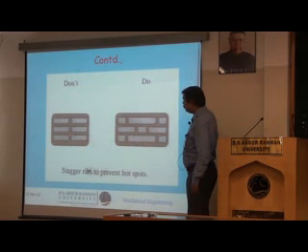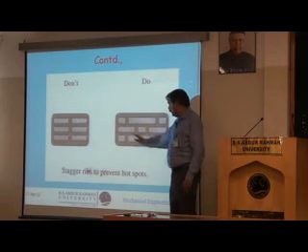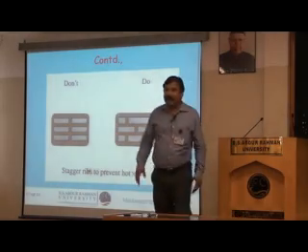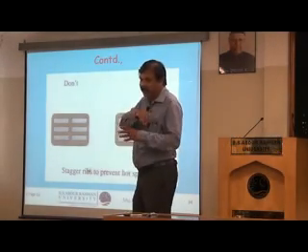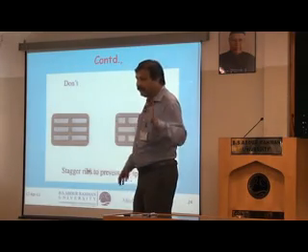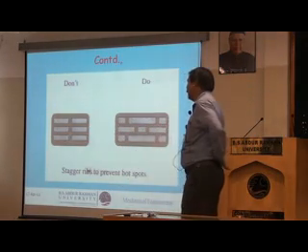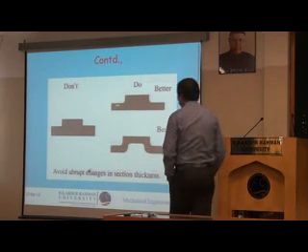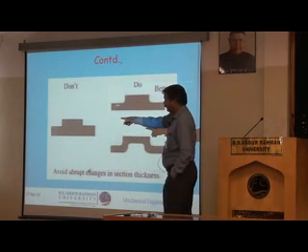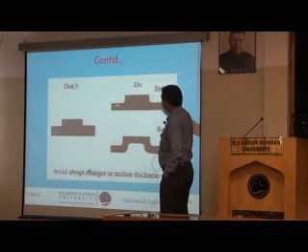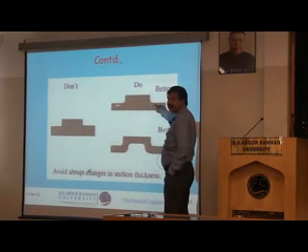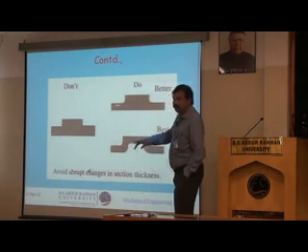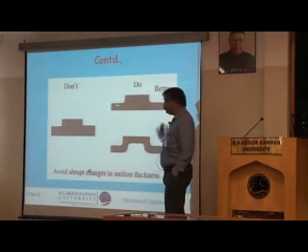Next. And similarly, ribs are to be staggered. When the ribs are aligned, that will provide a continuous discontinuity, and that is not preferred. All the ribs are to be staggered. Next. So that is one thing. There is a sudden change in cross section. This is better because I have provided a fillet. This is much better. I have ensured the same thickness here. So you have to think whether my design could be modified.